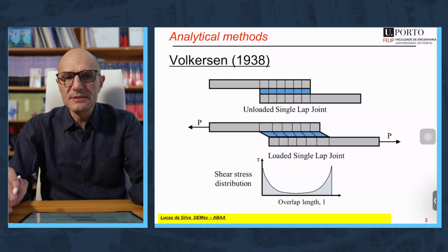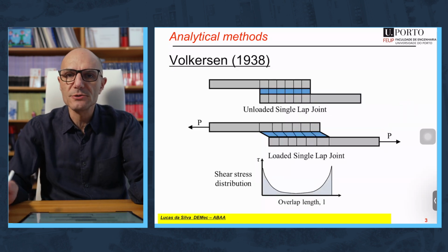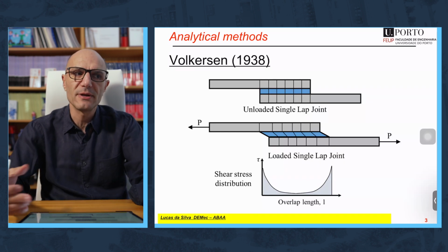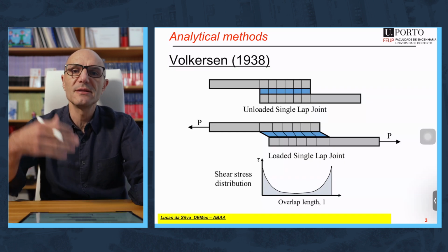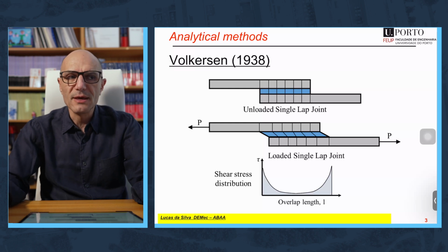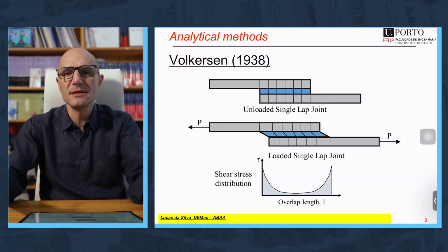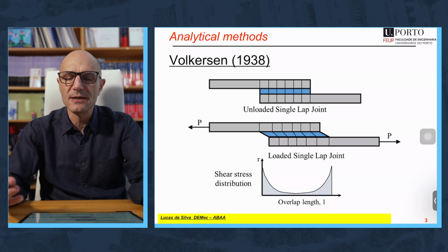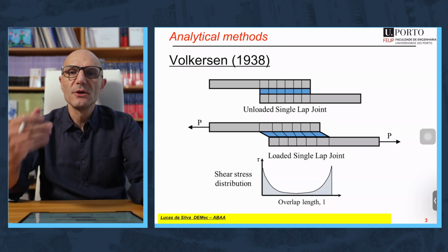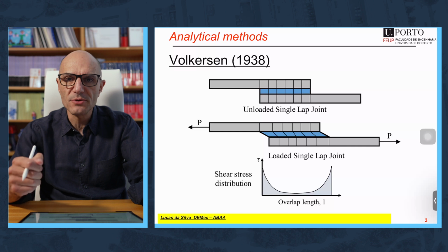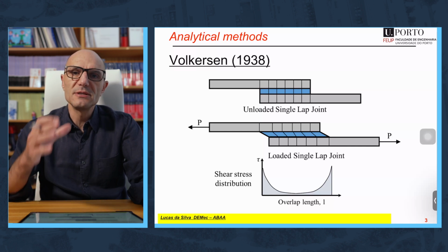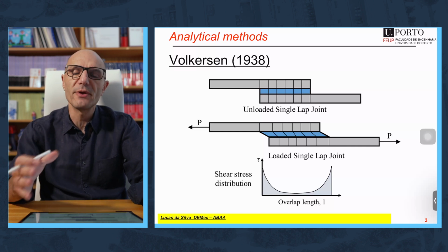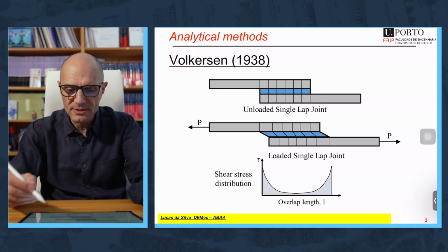Now, the problem is that the adhesives that are used for structural applications are not that flexible, not that elastic, not that deformable. I'm thinking obviously about the epoxy adhesives that are quite rigid. We are talking about 3-4 gigapascal. This is sufficient to deform also the substrate. And this will cause a differential straining in the adhesive, which is represented here.